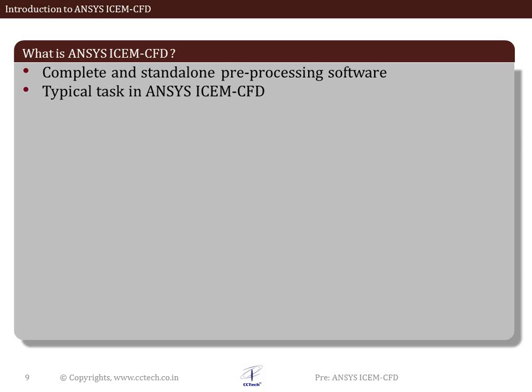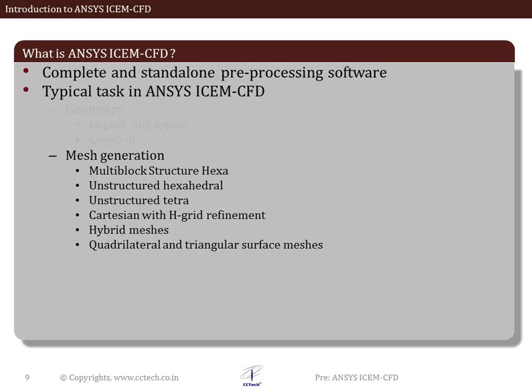The typical task in ICEMCFD involves geometry related activities, mesh related activities, boundary taggings, and grid export. The geometry activity includes both import and repair or geometry creation within ICEMCFD. Meshing activity includes creating the mesh using various meshing techniques available in ICEMCFD.